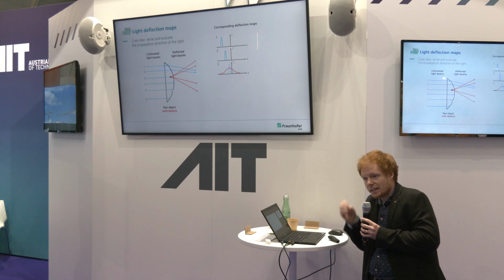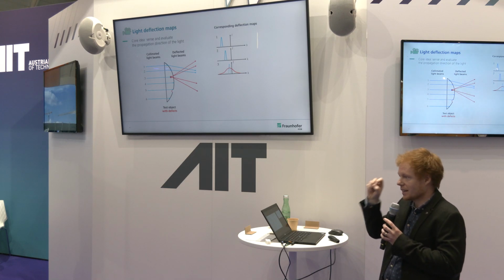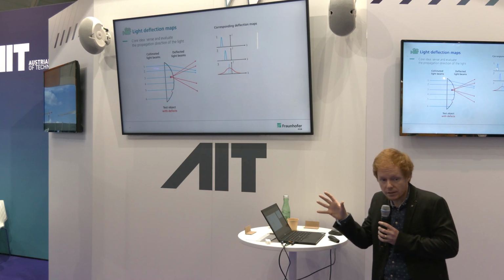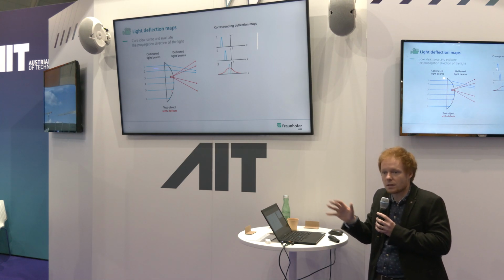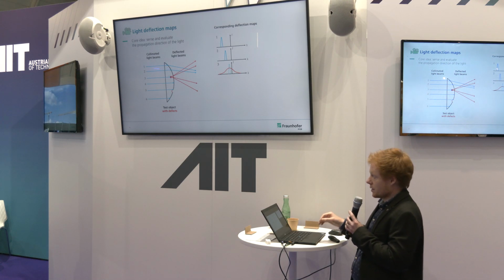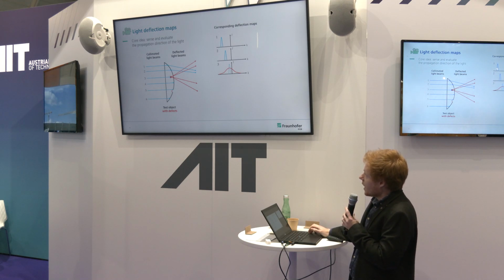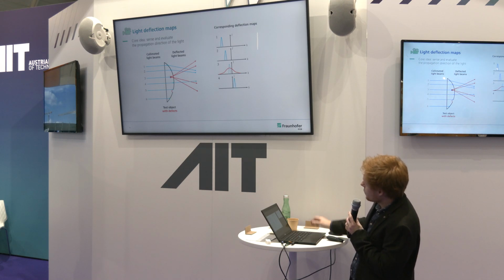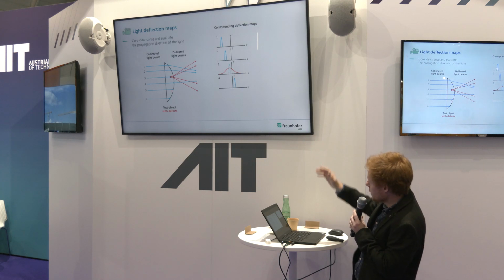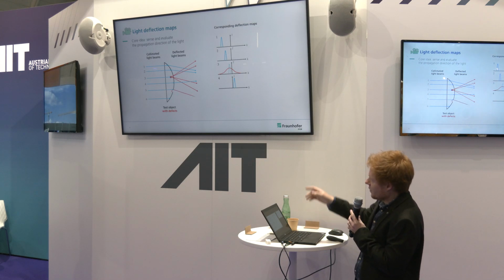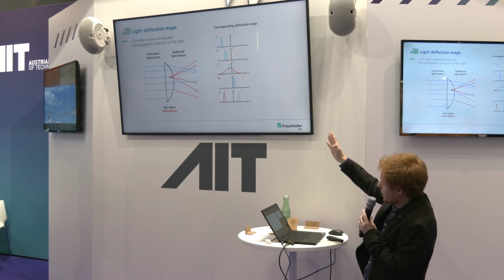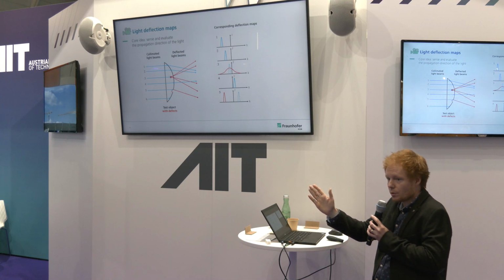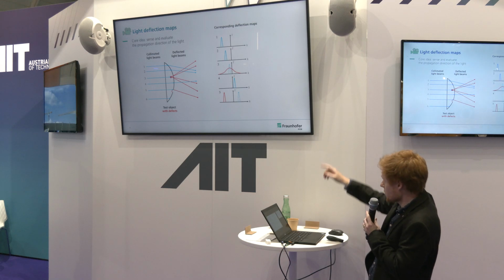And if we eventually hit a scattering material defect that scatters the light into multiple directions, we will have a very broad deflection profile, because we have multiple deflection directions present behind our object. Afterwards, we have a defect-free position, so the peak just continues to move. If we have a strong surface defect, we might get a strong repositioning of our peak away from its intended position.